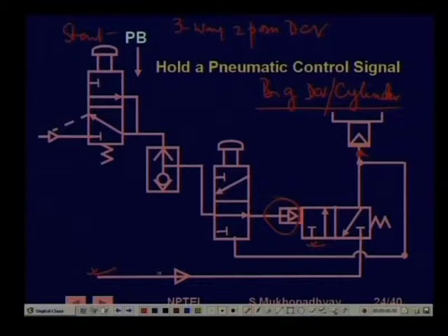In this position the control pressure will go to the final load. So, we have to apply pressure to this one to finally apply pressure to this one. Now, in the normal position, when this is not pressed and this is not pressed, they are in this block and this block. So, this is directly connected through this to discharge. So, there is no pressure here.